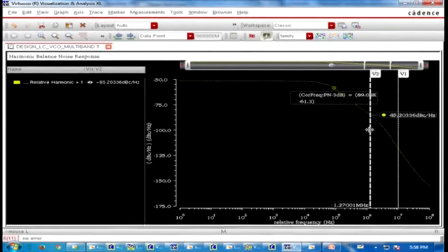So in this design, phase noise is not so important. We are actually using it for IO. Minus 85 dBc. No, I have also shown minus 122, but that is not our case. Our main purpose is the jitter performance and our serializer purpose. It is not about phase noise, because we are not going for some wireless communication.